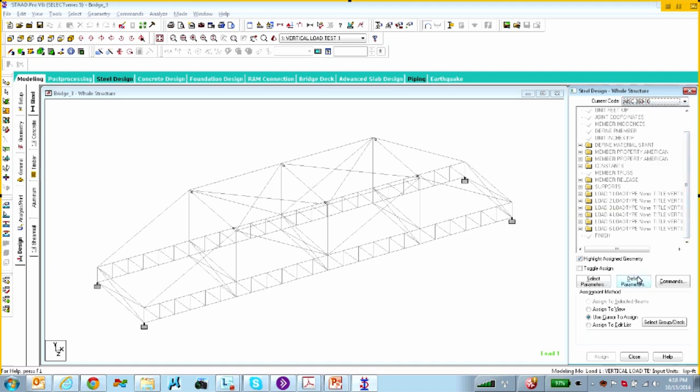You'd want to define any relevant parameters for your structure, things like yield strength, deflection ratio limits, since I know you asked about deflection, and interaction ratio limits. The default for that, of course, is 1.0, but you can go a little bit more conservative if you want. And that is done through this define commands process here. And then after that, we follow that up with a command structure.